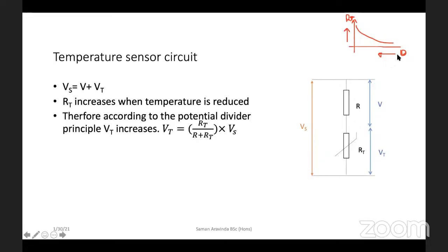Now, as the temperature cools down, what happens? Resistance increases. When the resistance increases, what happens to that potential difference? It also increases. So at 5 volts, what happens? If I have connected the heating mechanism across the thermistor, it will trigger and turn on. Am I clear? Okay.